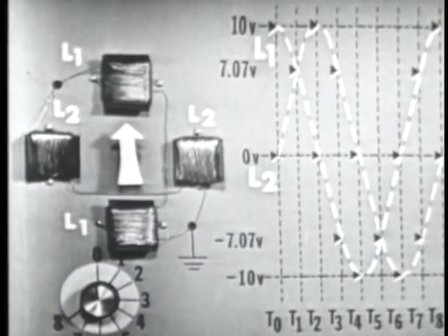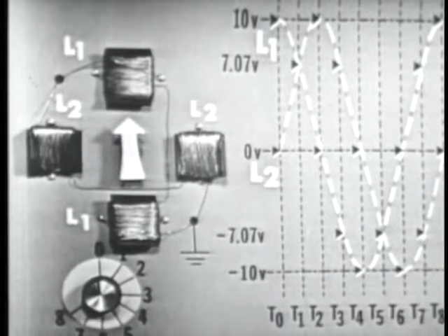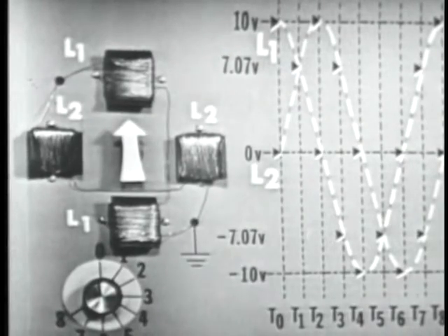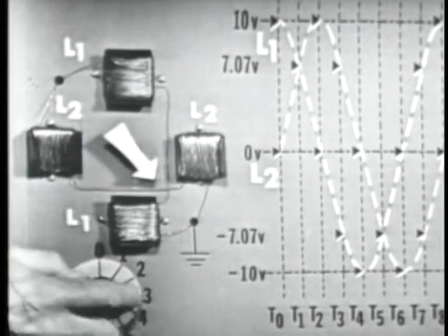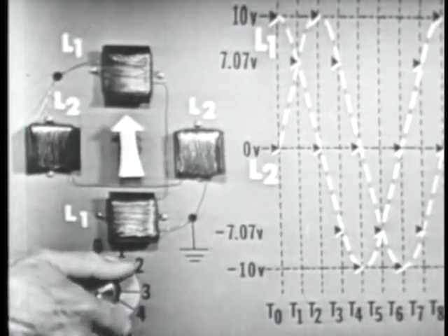All right, take number 3, Bob. Okay. A rotating magnetic field is achieved by applying out-of-phase voltages to the stator or the field windings, which we represented on this demonstrator. Now, you should point out, Bob, that the most effective phase difference to use is 90 degrees, as we did. Right.